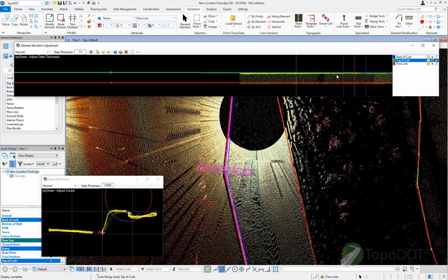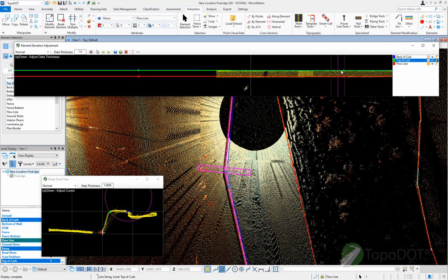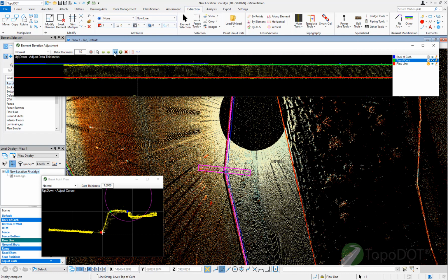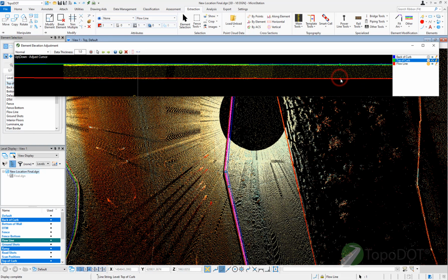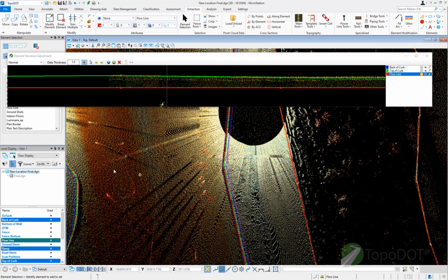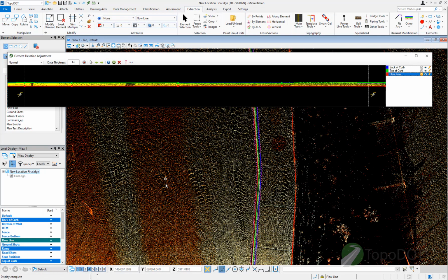Okay, so same here, the elevation may be just adjusted here and it'll be applied for most of the line, or you can just introduce it at any time by creating a new node somewhere here, right? And adjust. There you go. So that's that for minor changes.